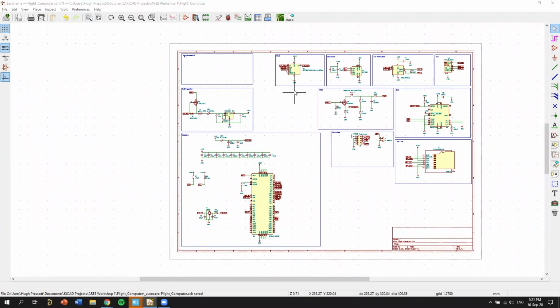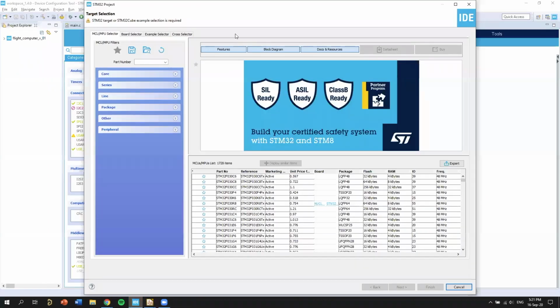What are the alternatives to thrust vector rocket control, like airfoil things? I mean, you can have active fins. Generally, with a normal rocket, you just design it so that it's stable, so you have no active components, and it'll just fly straight. But people work with active fins, which is a form of active stabilization. There's a lot of different ways you can do thrust vectoring, and then other weird things. You can have RCS thrusters, like little cold gas thrusters on the sides.